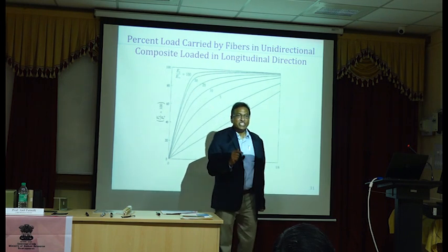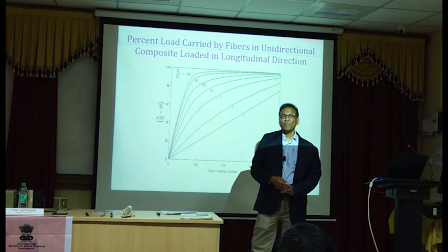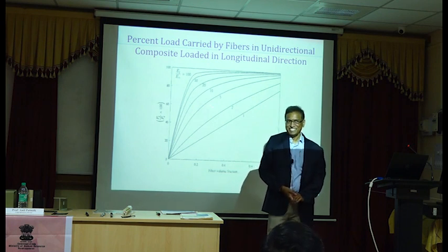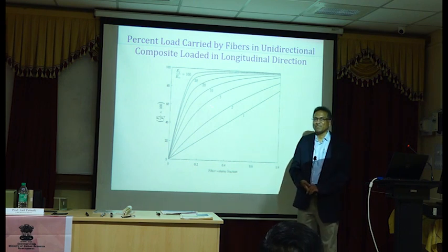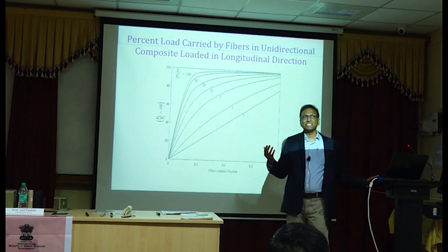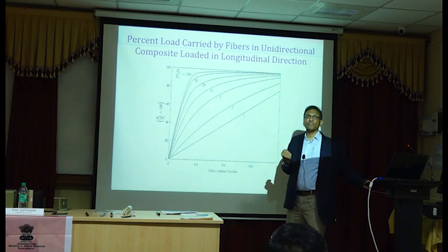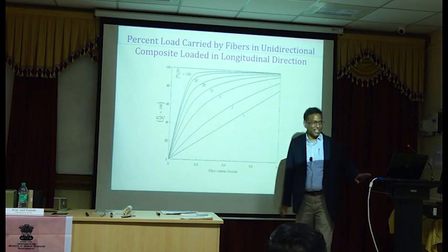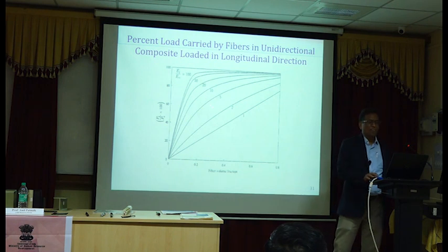That means it's an efficient composite, right? Your material is fully being utilized. Does it make sense? So you want to maximize, once again, the modulus of elasticity of the fiber to get most out of your material. That's the significance of this figure.